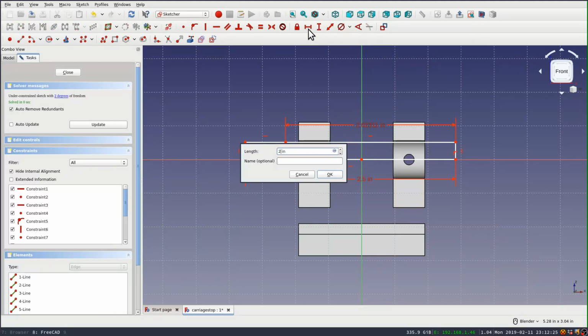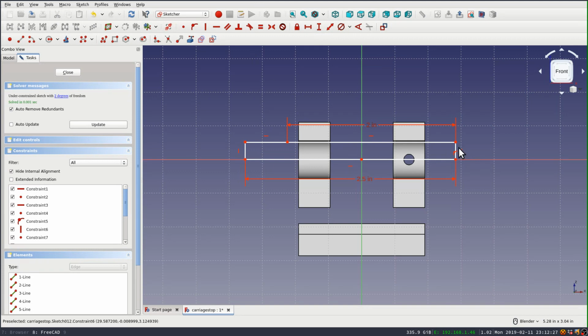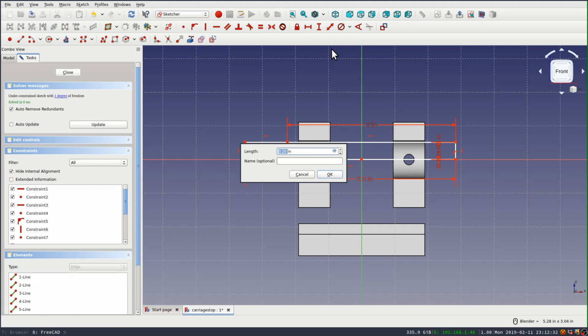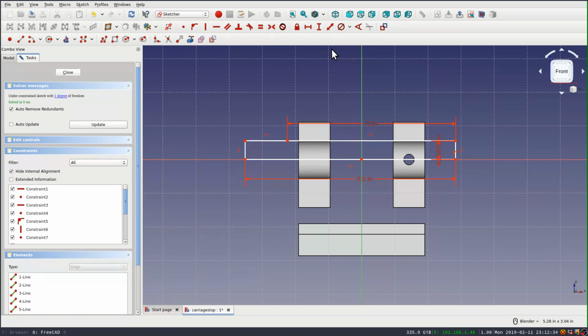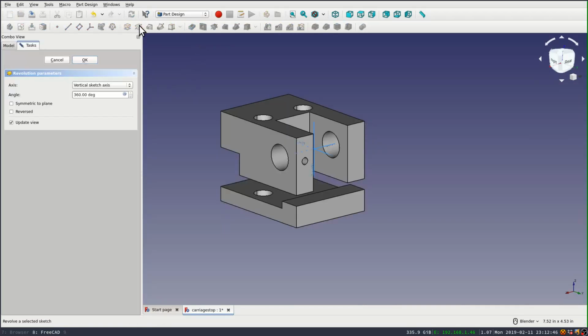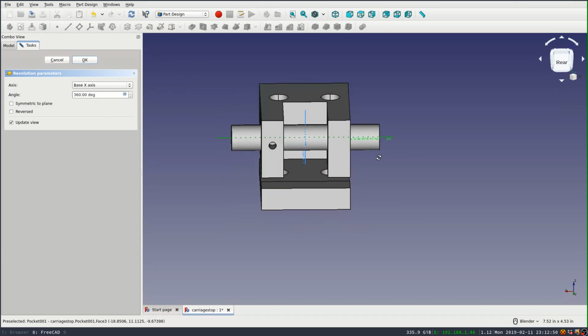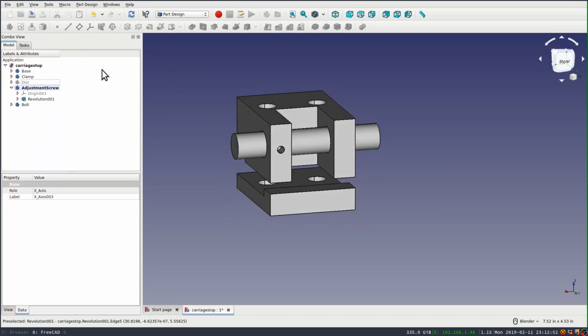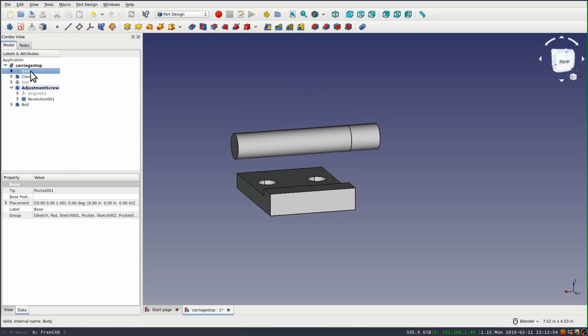And the threaded part is going to be 2 inches, and the height on it is 7/16 of an inch. I'll set it at 7/32 for the radius, and then it'll revolve around that x-axis. And we'll set these two to be symmetric as well, and that'll constrain it, and then we can do the revolve around that x-axis.